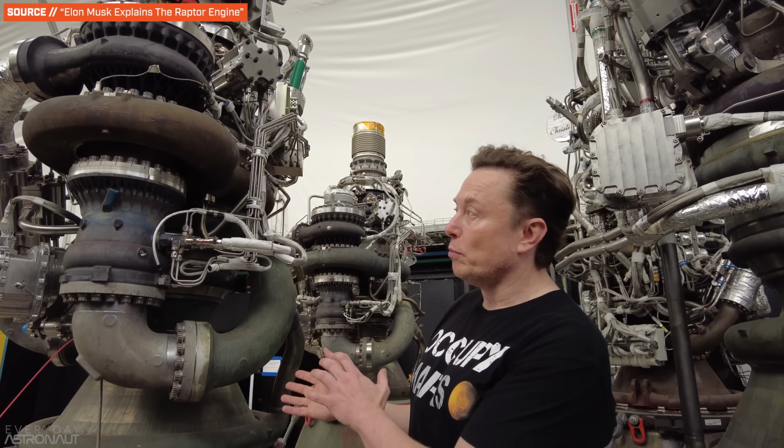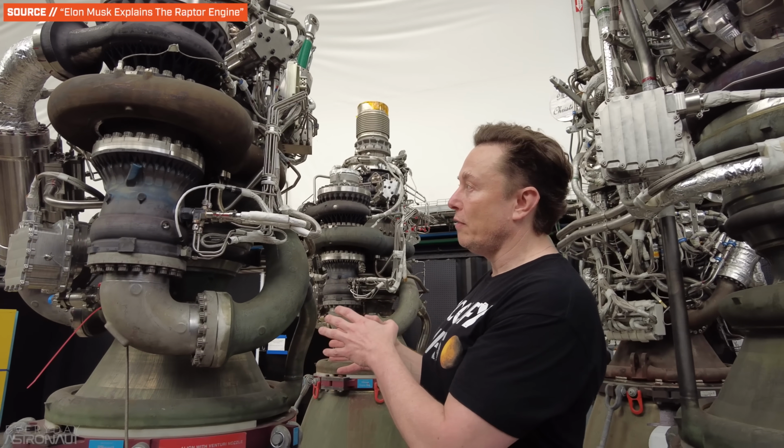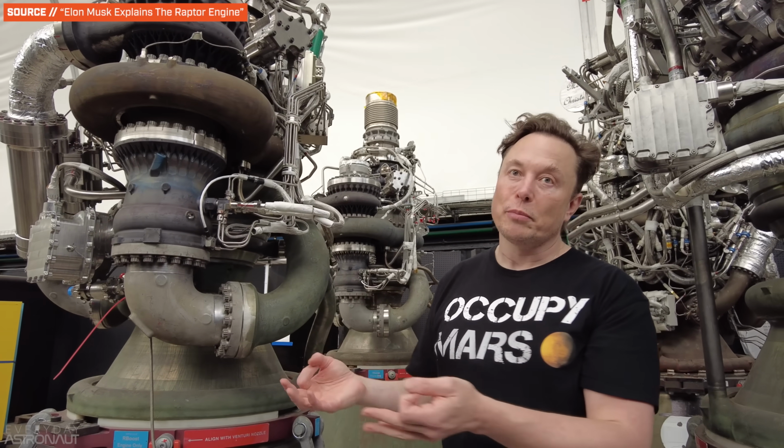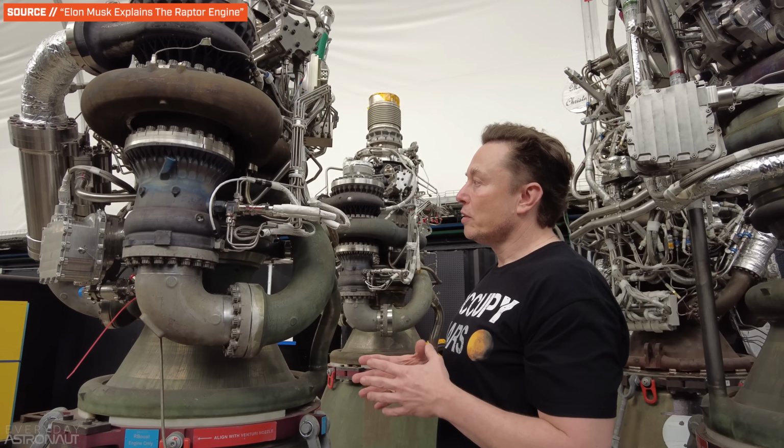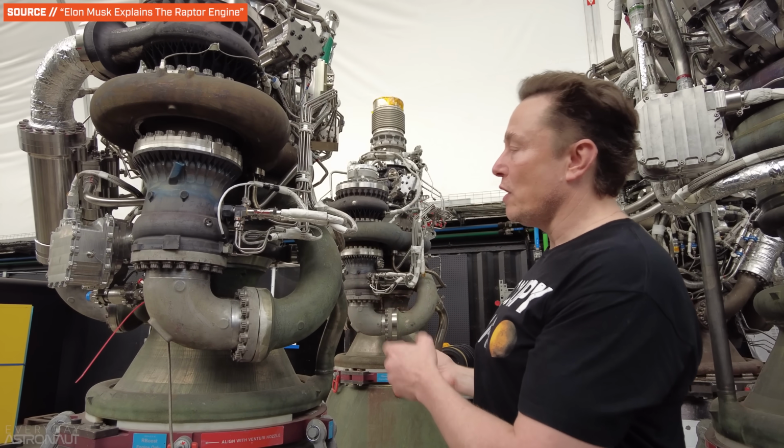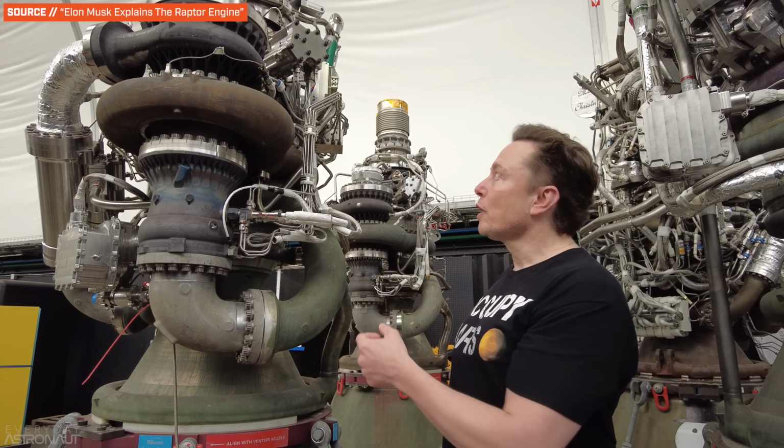So you can either have more main chamber pressure, or you can put less stress on the pumps. Although, looking at SpaceX's Raptor engine, they like to push it all as much as possible for the ultimate performance. But as attractive as the positive attributes of full flow are to engineers, it's often considered not worth it because of its extreme complexity.